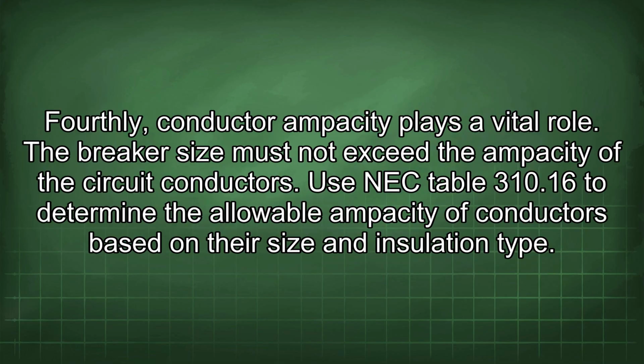Fourthly, conductor ampacity plays a vital role. The breaker size must not exceed the ampacity of the circuit conductors. Use NEC Table 310.16 to determine the allowable ampacity of conductors based on their size and insulation type.